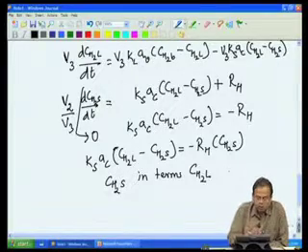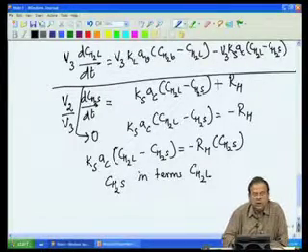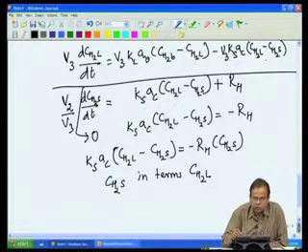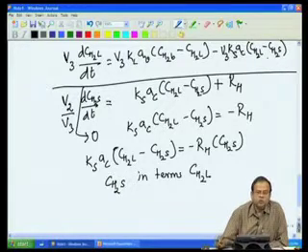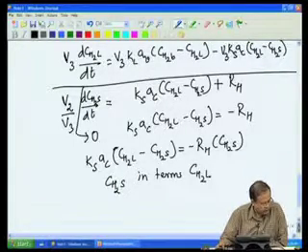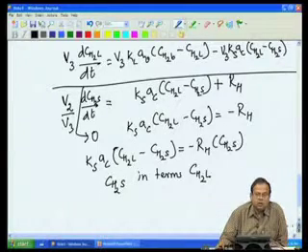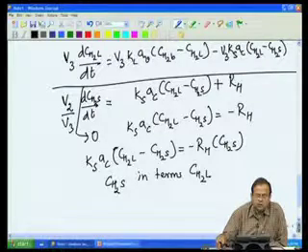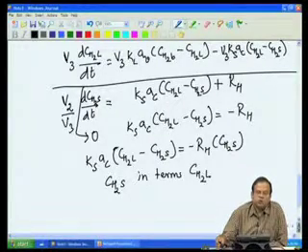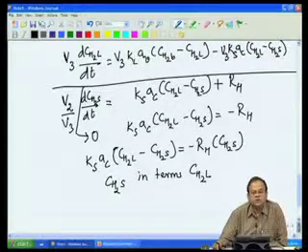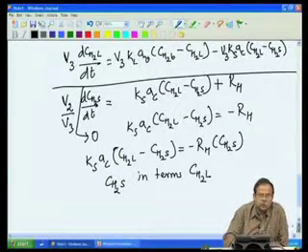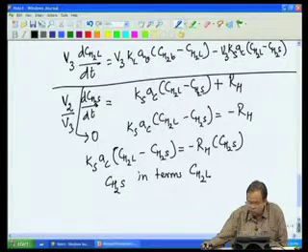That is not very difficult. We have already written a mass balance equation for that. In this mass balance equation, I can simply substitute for the right hand side, but we can also make a further assumption: due to the dynamics of mass transfer, the accumulation of hydrogen in the bulk is 0, or it has reached a quasi steady state, that is, dCH2L/dt is close to 0.